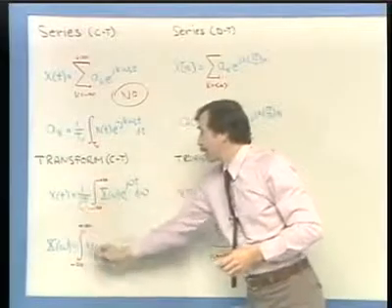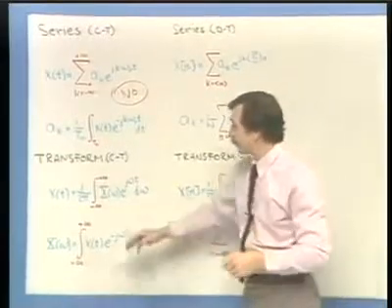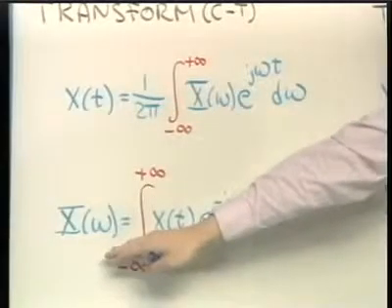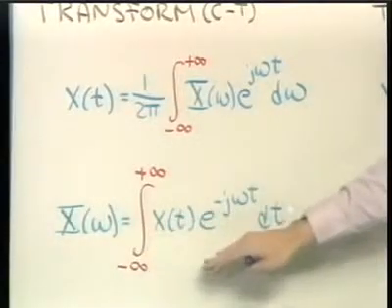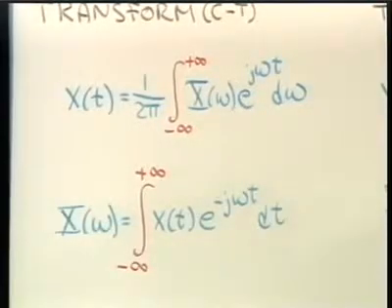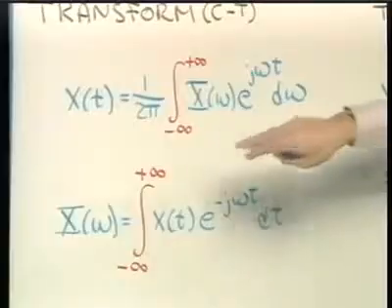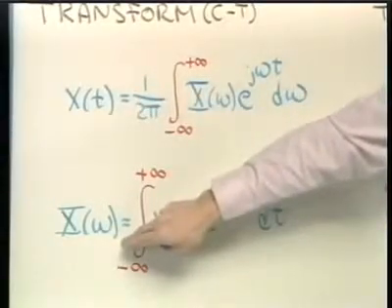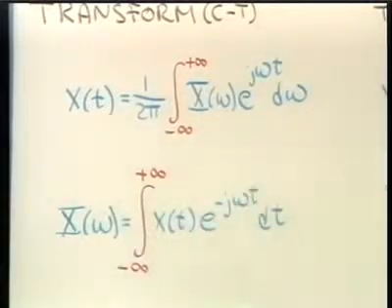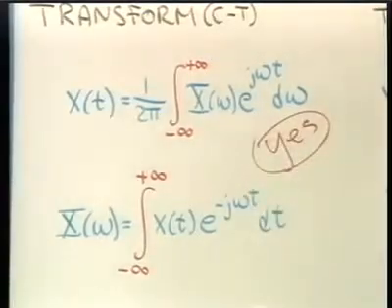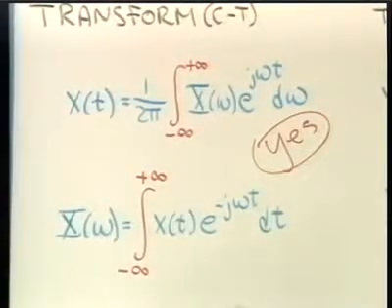However, for the continuous time Fourier transform, we're talking about aperiodic time functions and aperiodic frequency functions. And when we look at these two equations, we see very definitely a duality. In other words, the time function effectively is the Fourier transform of the Fourier transform. There's a little time reversal in there, but basically that's the result. And we had exploited that duality property when we talked about the continuous time Fourier transform.